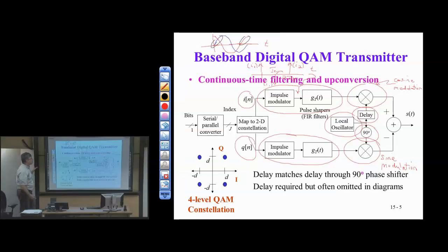But you can index into the lookup table with the correct offset. So if I had 400 entries, then it would be the right quarter length, a quarter of the period, to index into the same table. So here I get the same values in red as I get in blue. So one lookup table is enough, but I can also generate two lookup tables if I wanted to, using the memory.